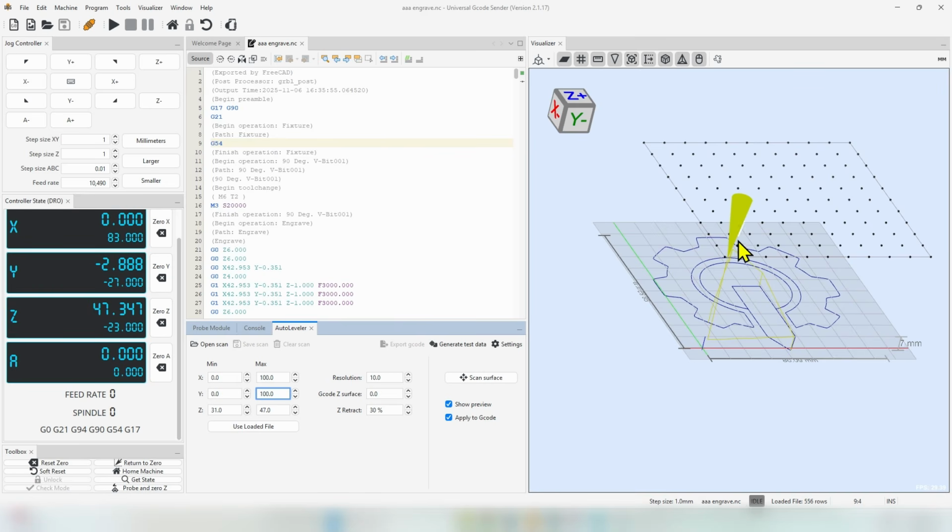The resolution is the distance between 2 consecutive points. If the surface is continuous, you can use a higher resolution because when creating the beziers based on the probing points, it will look exactly the same as the original. If you have a very bumpy material, using a lower resolution will help map that material correctly.